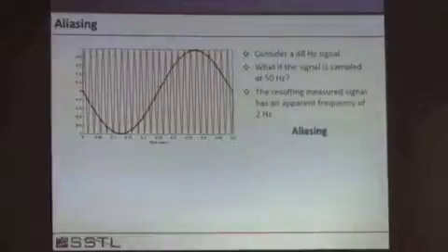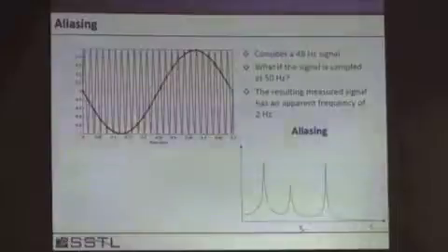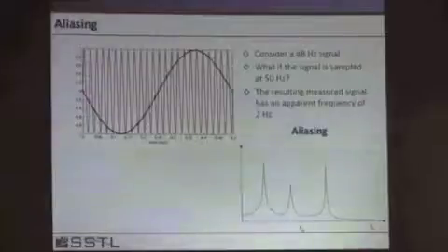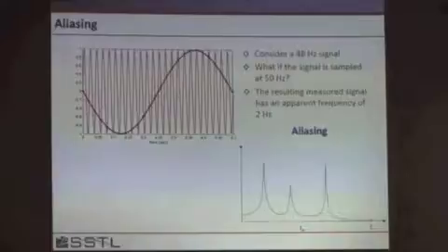This is the phenomenon of aliasing. So in terms of what that can do to our structure, imagine that this was the spectrum, the real spectrum of the response of your structure. Now, in real structures, you don't have a 3 degree of freedom system where you can say, I've got 3 modes here. There's usually a continuous spectrum of modes.